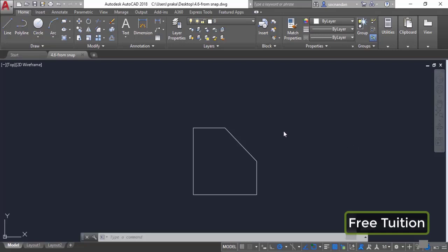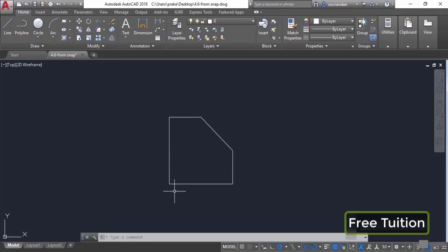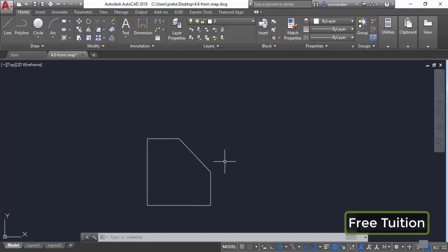So here we have a simple geometry. In this case, the length of this drawing is 10 units. The height is 10 units. We have this of 5 unit, 5 unit, and the remaining length of this slant line. Now let's assume that we want to make a circle somewhere over here, and we want to take the center of this circle in a predefined way. We want the center of this circle to be exactly at a distance of 10 units from the midpoint of this line, and that 10 unit line should be inclined to an angle of 30 degrees. For that, obviously we can make a line here. So we can start a line from the midpoint.